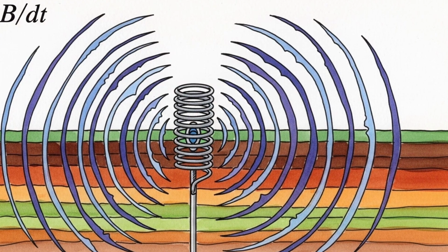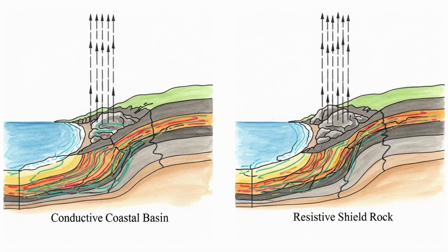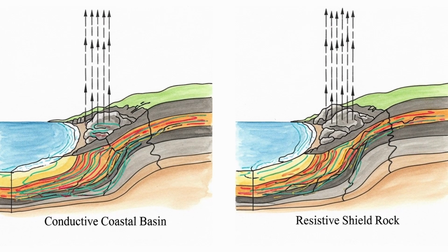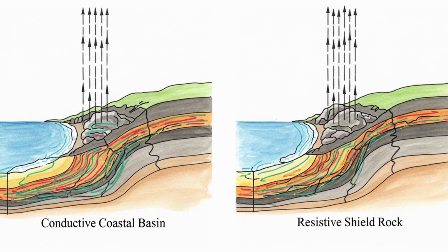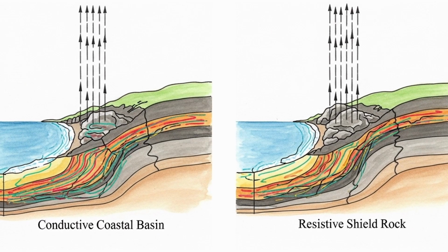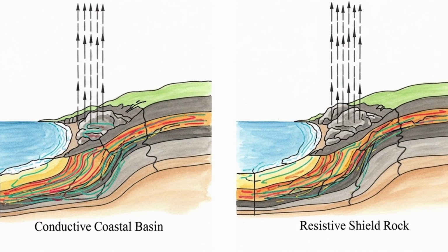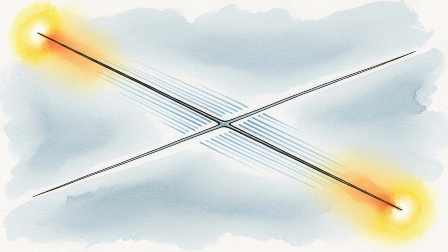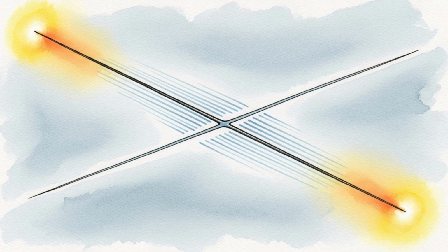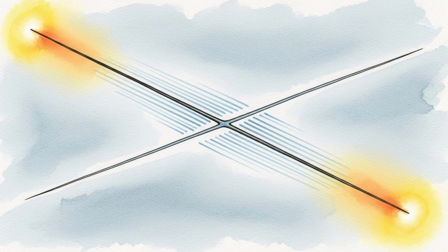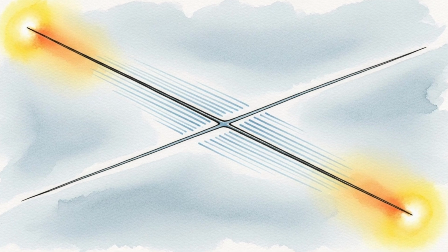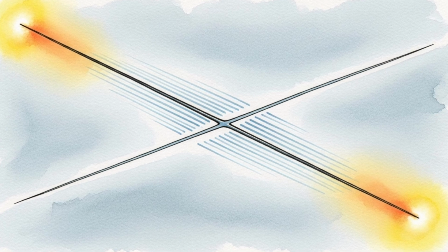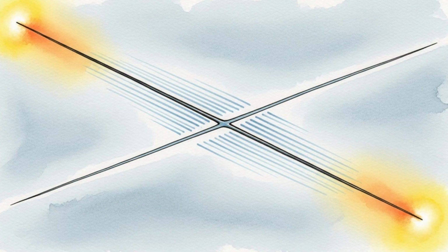In March 1989, a severe storm produced large geomagnetically induced currents in parts of North America. The result included the collapse of a regional power grid after transformer saturation and protective trips. The event showed how reactive power demand can rise quickly when many large transformers enter a stressed state at the same time. Restoration took hours and required careful sequencing. This case connected space weather directly to modern power system operations, planning margins, and the need for procedures that match fast external disturbances.